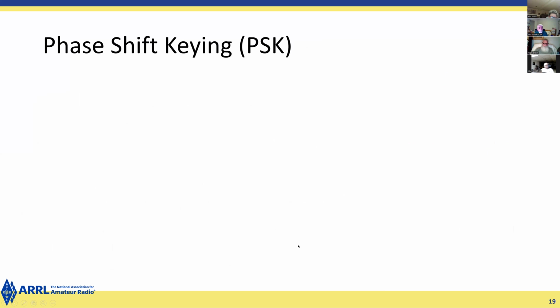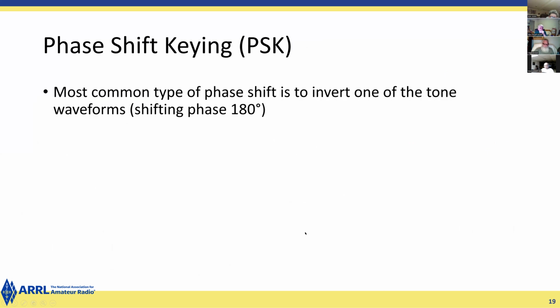Phase shift keying is a little bit different. The most common is to take a carrier and invert the phase, in other words, send it at a 0 degree or 180 degree phase. And there are a couple different ways to do that. The idea is that it's fairly easy to detect if you have a constant carrier reference in the receiver to measure the phase against.